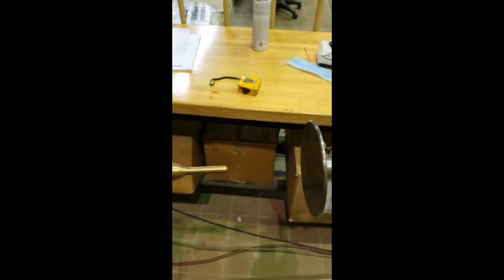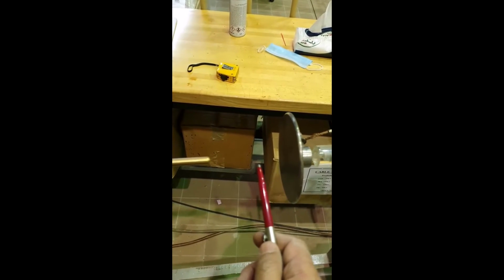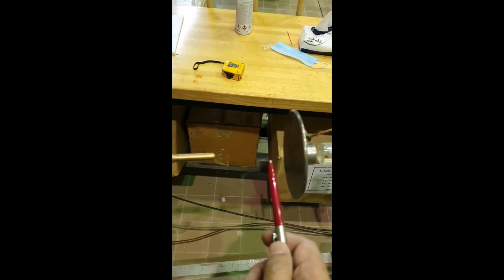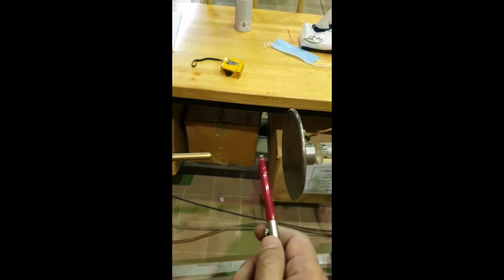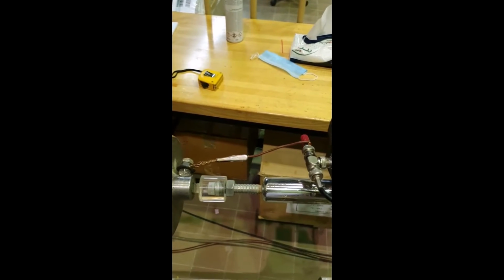Now first, before you connect anything, any oscilloscope for detection of this waveform, you have to find the breakdown voltage of this gap. It should be far higher than the corona voltage, so that you don't get any breakdown in the gap. If you have a breakdown in the gap, the whole signal will go to your oscilloscope and it will get damaged. So this is the ground point for this plane, and it is going through this resistor. This cable is going to the oscilloscope. This resistor in the box is going to the ground here. So this is the ground terminal for this one.